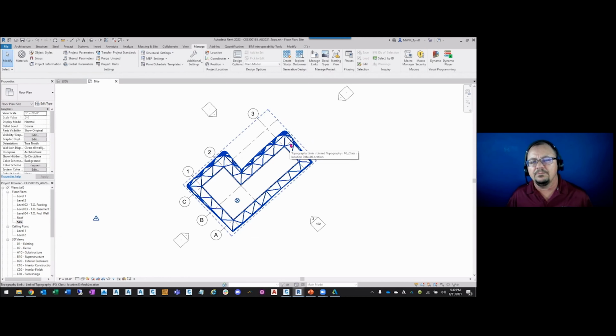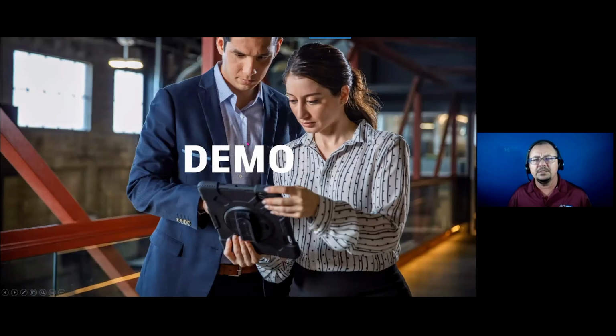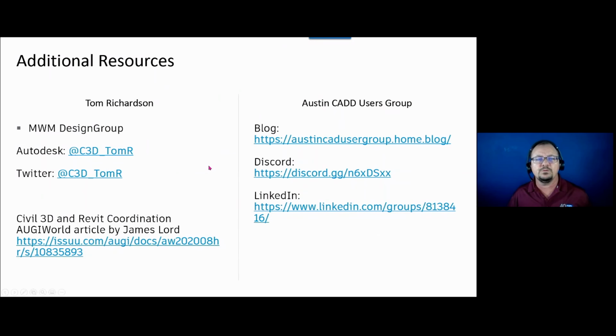And again, you may have to work with the elevation on that XML file to make sure that it comes in at the correct elevation, or make sure that the Revit model is moved to the correct location in relation to the site. And that would be done through Relocate Project. So that's the process. That's the demo of those 4 learning objectives.